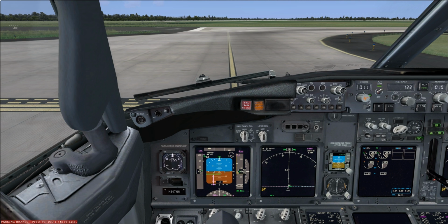And as he passes through the downdraft, he gets into the tailwind, and of course, because he lost the headwind from before, his airspeed is already low. You get into the tailwind, your airspeed gets even lower, and your aircraft would basically stall. So all this is an example of what would happen if you approach the landing.